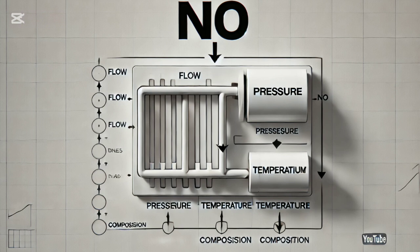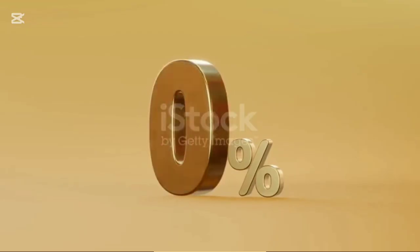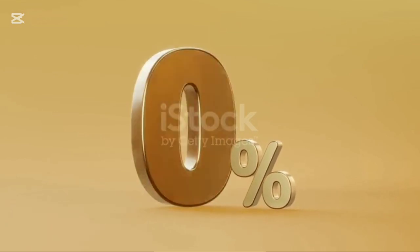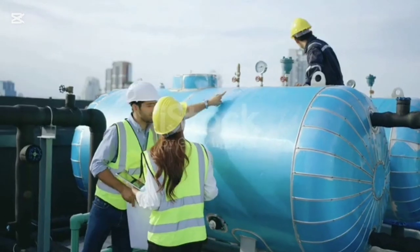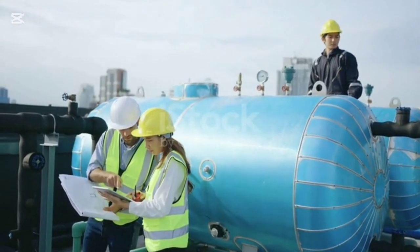Level. Next parameter is level, and the guide word is no. We are taking just one guide word, no, and applying it to all the parameters. Applying no to level will result in no level, the absence of level, which could indicate a completely empty tank or a vessel. Deviation: no level in a feed tank could starve downstream equipment and disrupt the operation.